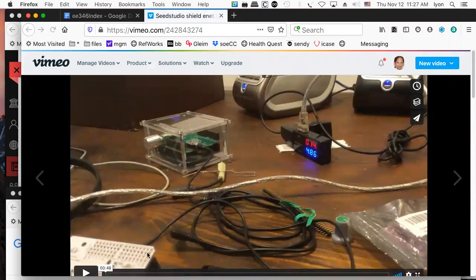So how do you stream it? I don't understand it. Well, what it's doing is it's printing out to a socket, and Telnet gives you a socket. Then you can have an input stream and an output stream, which is just an unformatted sequence of bytes, but it so happens the bytes represent characters. So when you do the print, it's just like printing to the serial port. Effectively, you're printing to a socket. So it's an output stream, just like printing to a file or printing to the console.